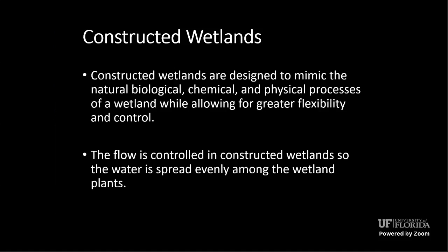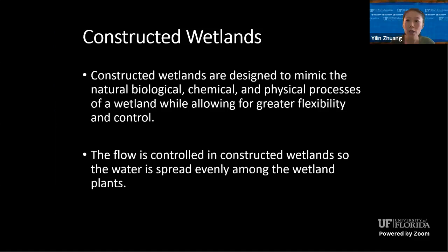It is important to maintain an even cross-sectional flow throughout the wetland to assure proper treatment. The wetland has the possibility of becoming plugged with debris and organic matter, which will prevent even cross-sectional flow.